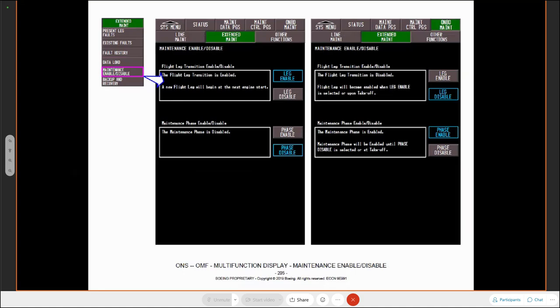It's software based. So if you're sat at home after your shift having a cup of tea or a cup of coffee or even better, a pint, and you're thinking, oh, hang on a minute, did I switch that onboard maintenance function back on again? And you can't remember, it doesn't really matter, because once the aircraft goes airborne, it automatically switches it back on. Okay, it's just a soft switch. That's all it is. It's a software switch.